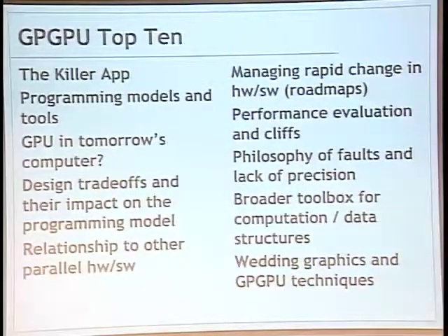That's a design trade-off, though, because if you do something in MIMD, then you're going to pay the price in terms of hardware. You're not going to have as much data path hardware as you would if it was SIMD. And so what's really the sweet spot there? There's a lot of design trade-offs that you do, and they are going to affect the programming model. And this is sort of the place where the hardware and the software intersect. So a place where a lot of research can be done.